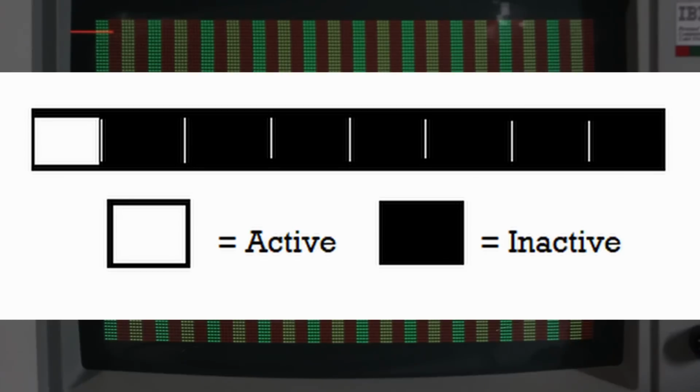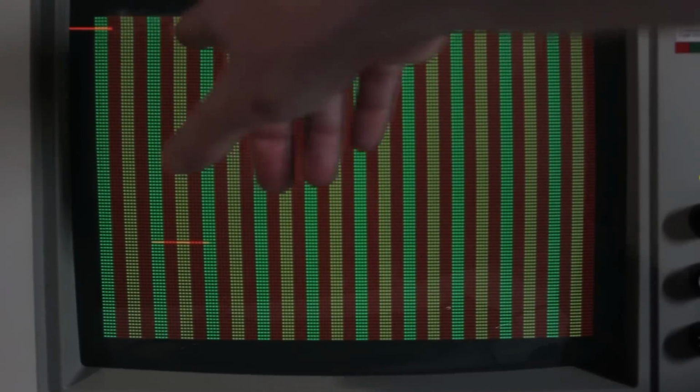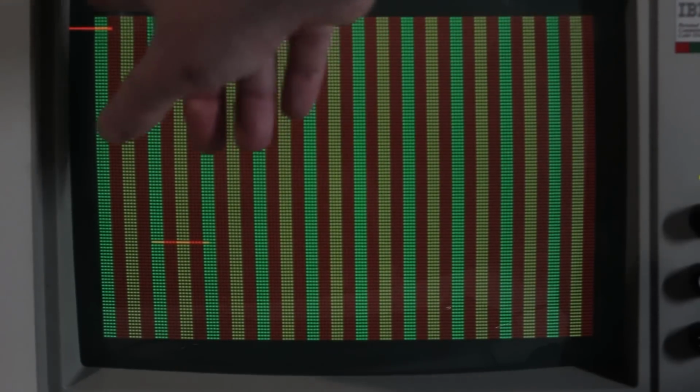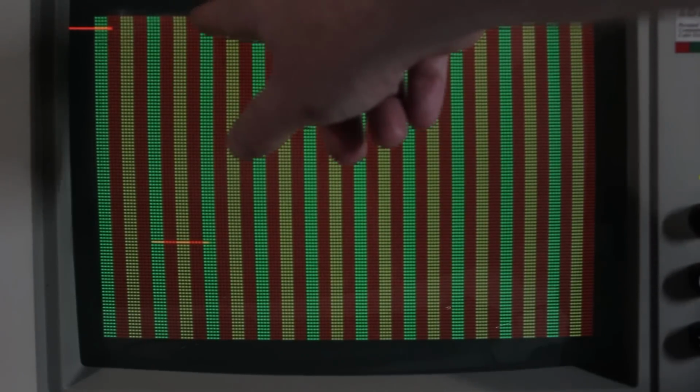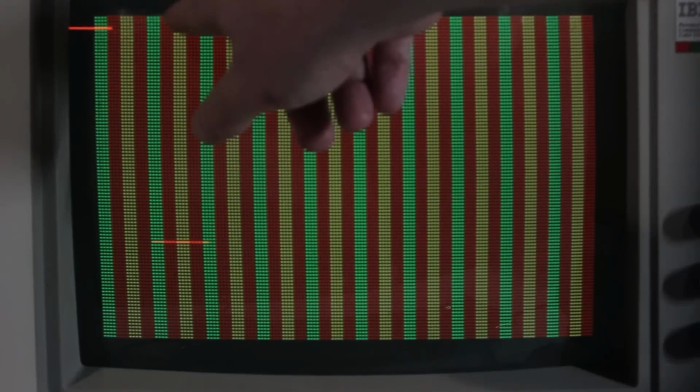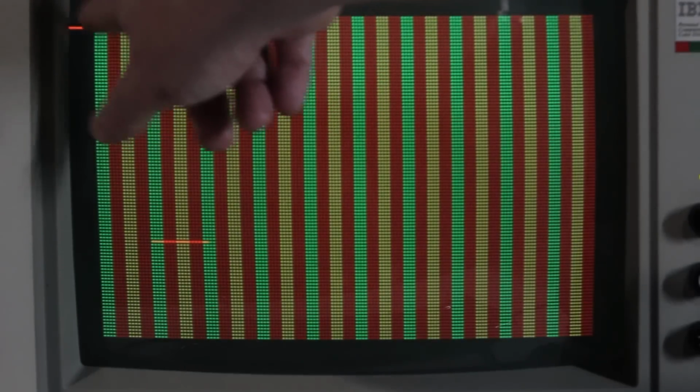And then we have a loop which is precisely 1 character short of a CRTC frame. So in other words, just 7 characters in length. And so every iteration of that loop, it's effectively going to be stepping back by exactly 1 character in that small CRTC frame. And I just do that until I'm in the single active character.